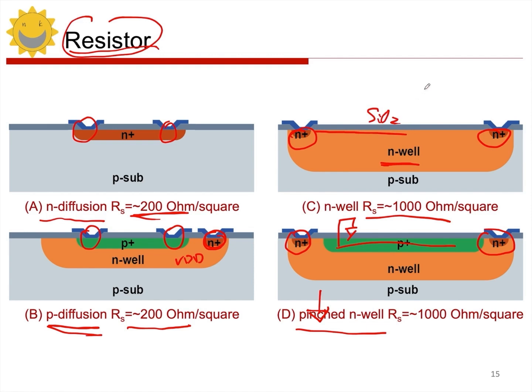When it comes to that, what will happen? There will be a lot of what we call, what's it called? Dangling bonds. Yeah, dangling bonds. So these dangling parts are defects, right? The defects in the lattice will become traps, releasing or capturing carriers, and in this case, it will affect the electrical noise characteristics. Because these dangling parts will randomly release or capture charge, the current on the resistor will definitely fluctuate, so it will increase the noise of the resistor.